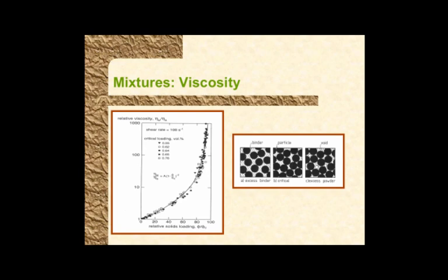So another aspect of mixing is how to control the relative ratio of powder and polymer within a very narrow window, because small errors in volume fraction can result in large errors in viscosity. So the ability to make or not make a shape can be quite different if your mixture is not homogeneous enough, uniform enough, right?